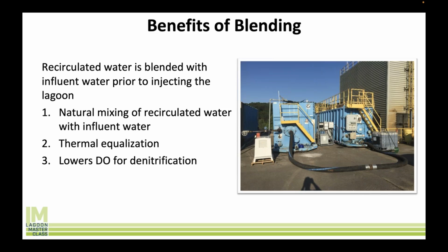However, once it flowed out of the back of that second tank on the right-hand side in that picture, what we found was between the back of that tank and the ultimate discharge point into a storage pond, they were getting a ton of nitrate removal. They were getting almost 10 to 20 milligrams per liter of nitrate removal. So somehow that denitrification occurred in the pipe itself. So that's why I came up with this idea of blending, and I think it works really well.